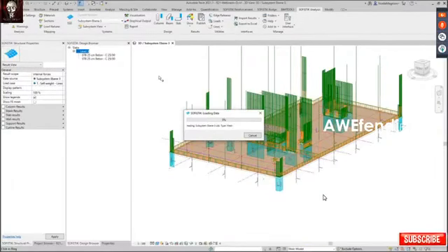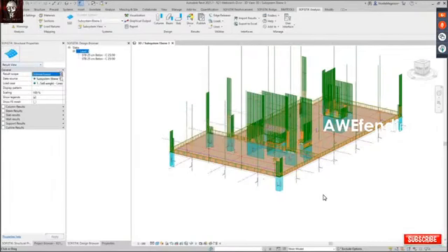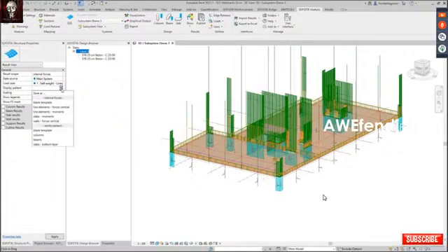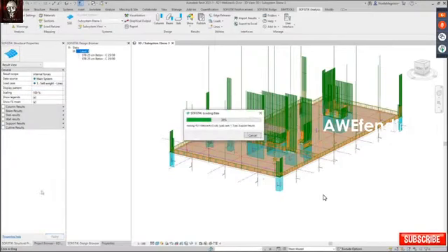So this show result is really a live reading of the content of the database and a display of this result in Revit. It appears here as a new structural property, which is called the Revit view, where you can define what kind of result you want to see, what kind of data source you want to read from, the load case. You also have some templates, where you don't have to click all the options and you can already prepare and have them really quickly available.